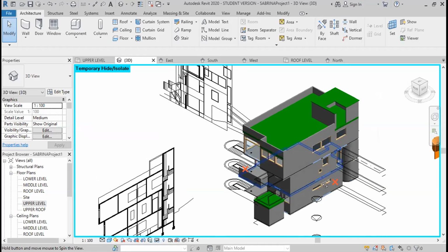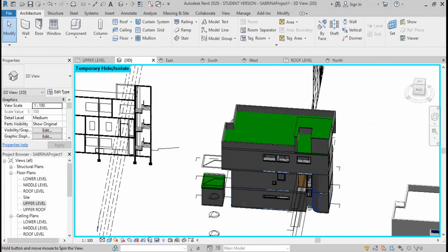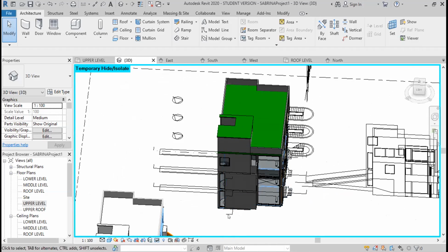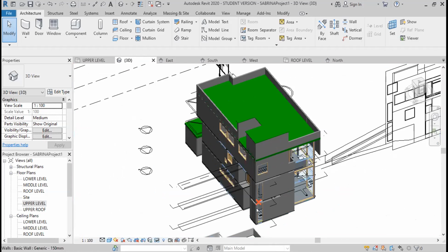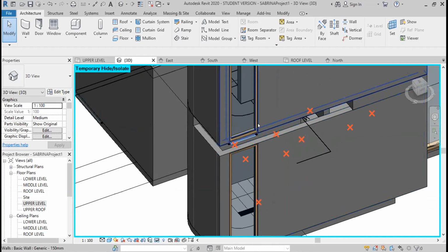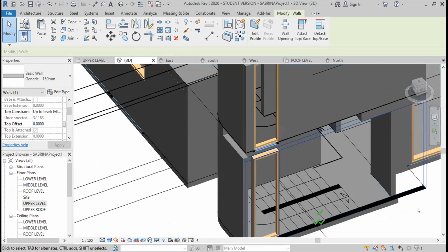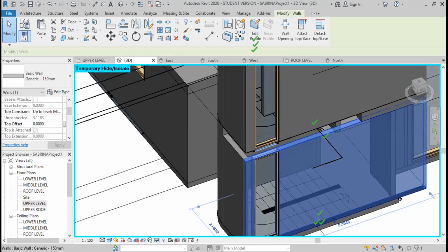Here. There is an opening here. Go back. Rotate back. Here. Rotate more. Go back. Oh, one second. Try to zoom here. See, there is an opening here. Oh, this is because this is the stairs, so we didn't do the. No, but now you can still connect the walls. If you select the wall, you will see actually. Select the wall. Place up to middle level. When you select the wall, basically I can see here there is kind of a rectangle, but why can we not see this? Anyway, you can edit the boundary here.